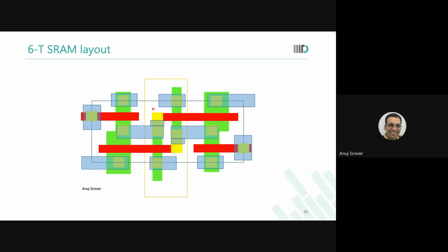So we'll talk about what we call replica paths, dummy cells, and so on. So in dummy cells or in replica paths, you cannot touch anything below metal 1. All the changes that you may want to do are to be above metal 1. Now, only for poly, we may make some exceptions, but that will be on a case-to-case basis. If you want to do it, you have to come and check with me, but in your company, you will have to go and check with the process teams over there. Is that okay?